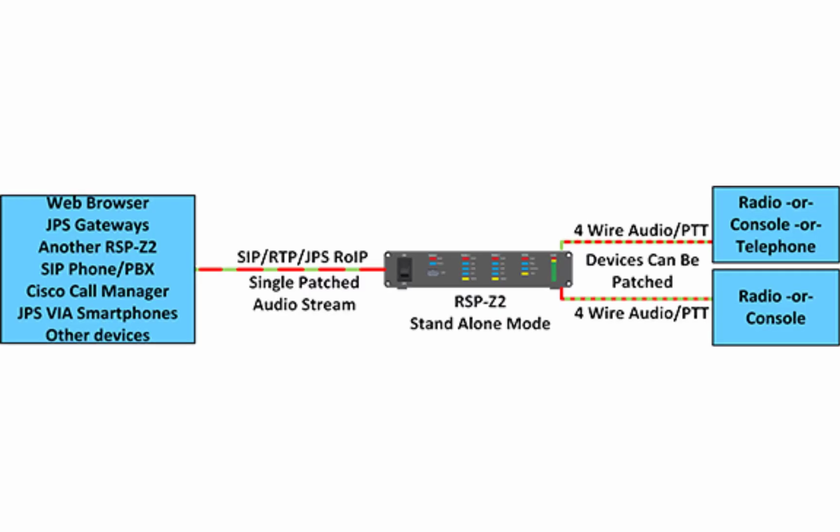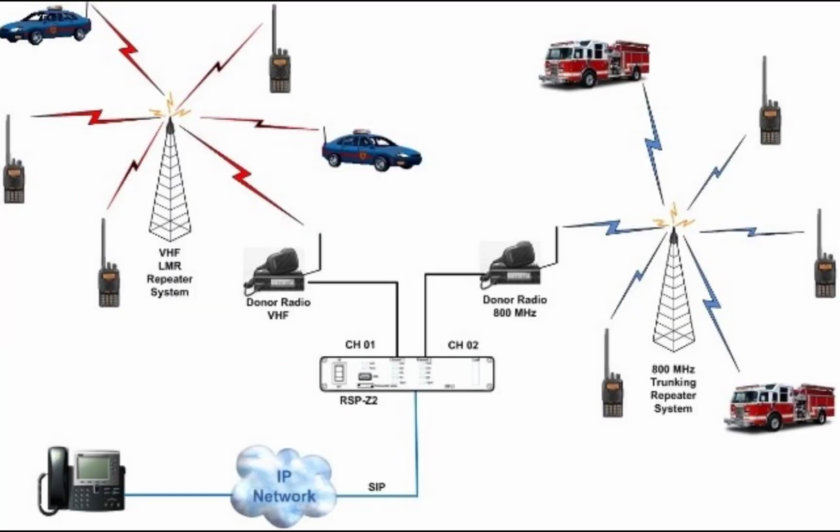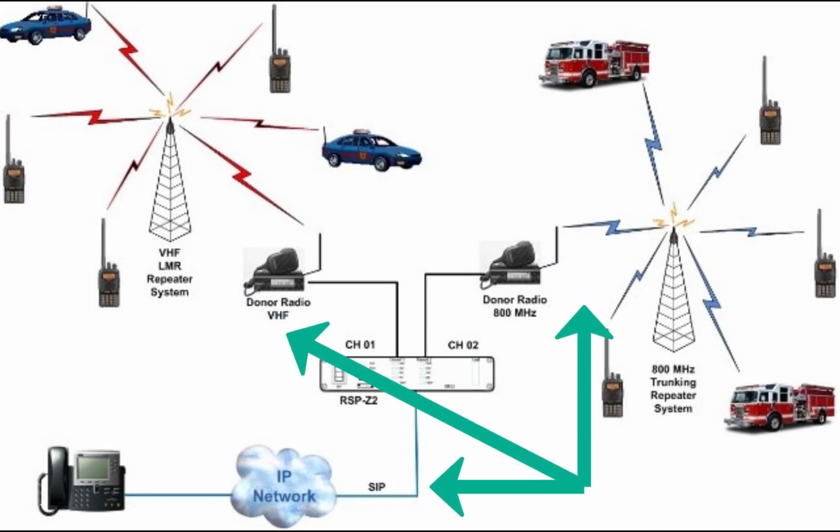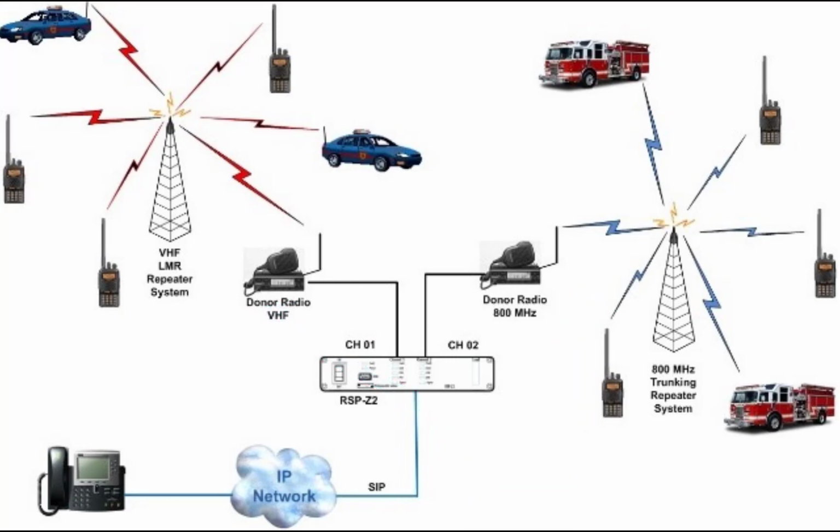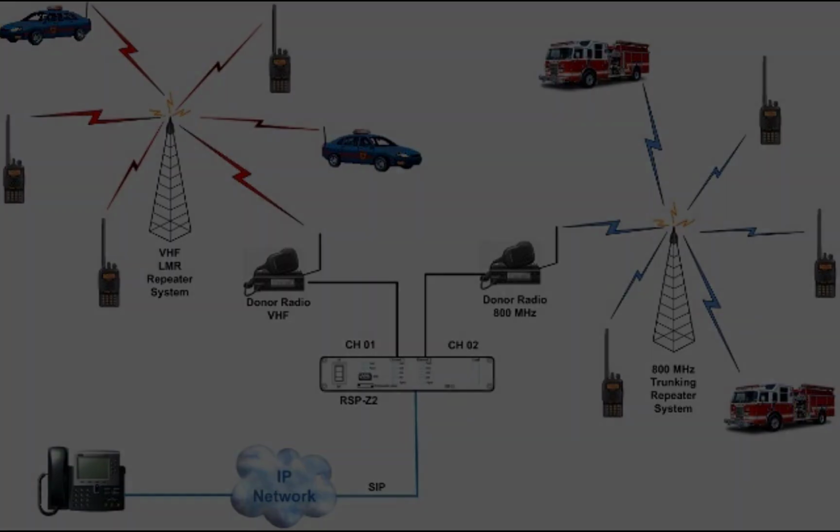Now let's discuss the cross-connected with backhaul. This is a combination of the independent pass-through and cross-connected configuration. Only a single backhaul interface is needed because it is interfaced to the combined cross-connected audio of the two local channels. The diagram shows one of the many ways the backhaul channel can be used, as a SIP channel allowing a supervisor to dial in by a VoIP phone. All three channels are connected together, so the caller will hear anything in either channel, and the supervisor's speech will be retransmitted in both radio systems. The diagram shows the cross-connected with backhaul capabilities.